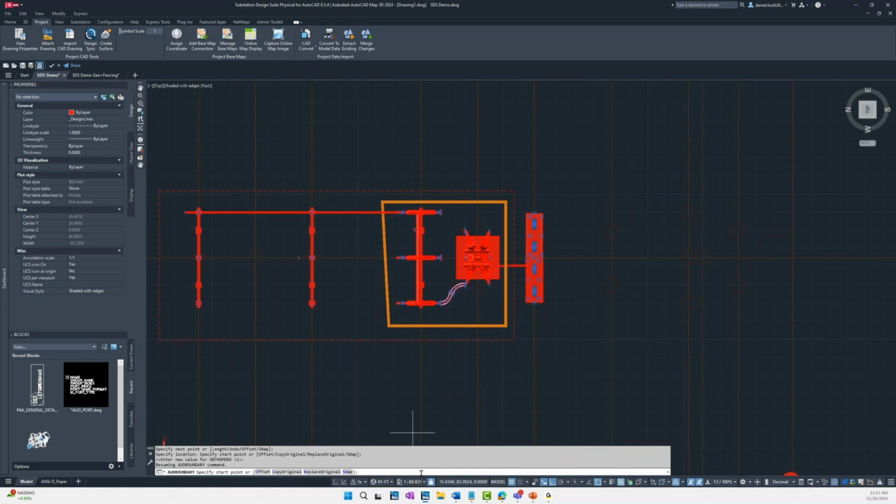So we've created our boundary. Now we're going to edit that boundary, AUD boundary edit, select our boundary, and then we're going to select within. So this will grab all of the elements within that boundary, all of the features. We can even highlight them to show we've got all these features highlighted and selected within this boundary.